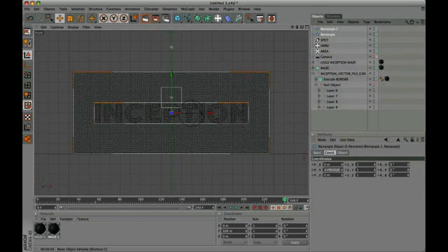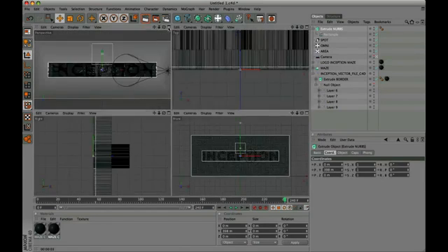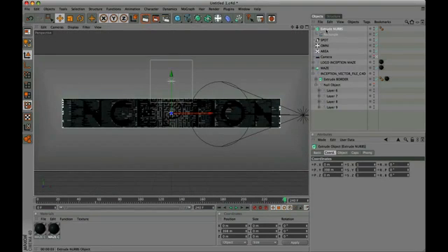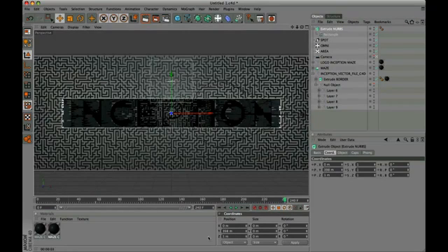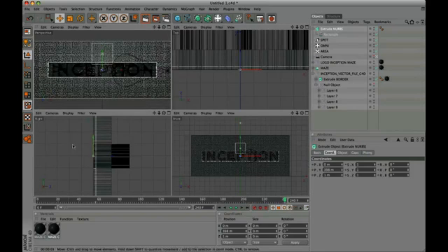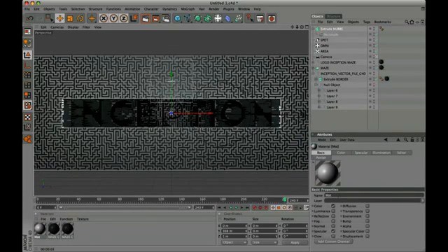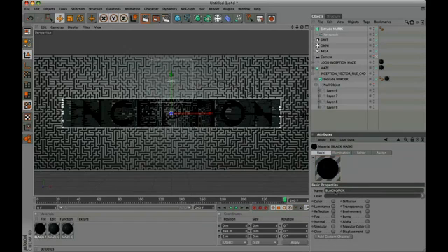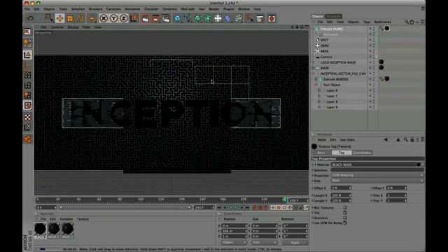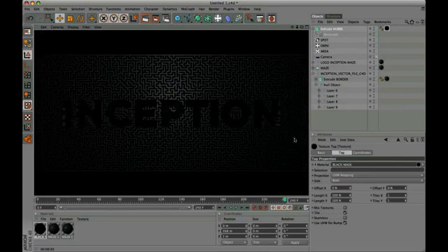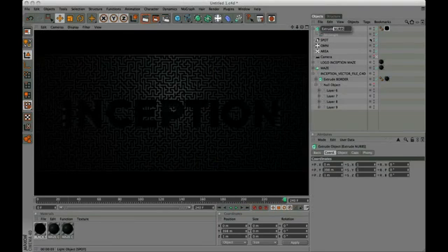We convert the rectangles into two splines and group them using Connect. We apply Extrude. Go to Camera Display and move the object along the Z-axis by 1 meter, so it's placed under the maze and creates the necessary mask. Create a new material and rename it Black Mask. Disable all, and we apply it to the mask. We make a render to visualize the final maze effect. Rename the newly created object Extrude Maze Mask.